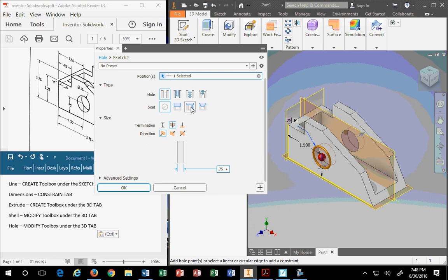And the last one is for woodworking people, which is a countersink, which is a fluted type hole, so that if you have a wood screw, which has that fluted tapered side walls to it, it can be flush to the surface as well. They do it in machining, but not as often. So in our case, it's just a hole.